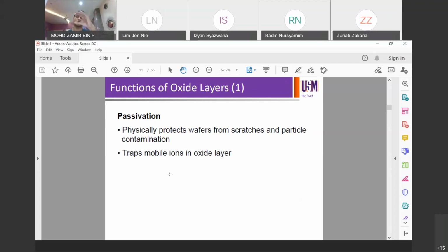Maksudnya, you might want to sandwich the whole oxide and actually break the oxide down into maybe, I don't know, 3 steps. For example, if you have silicon here, you might want to have your dry ox first, followed by wet ox, followed by dry ox, so that you have higher quality oxide first, then lower quality in between, and then higher quality at the other end, so that you sort of sandwich the oxide within the whole bulk of oxide.